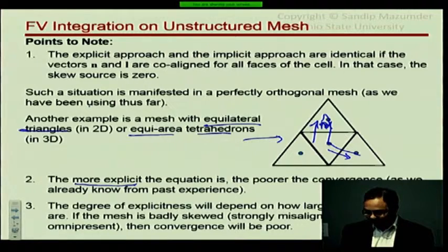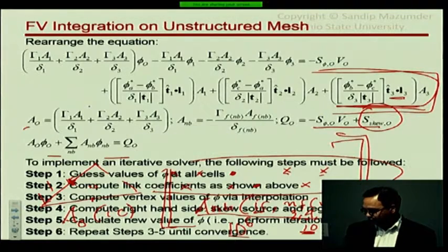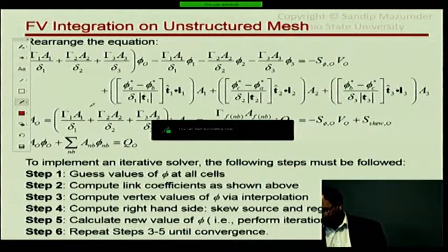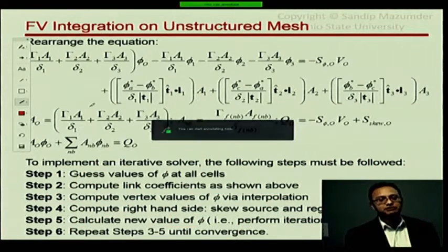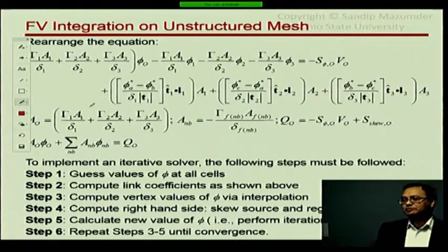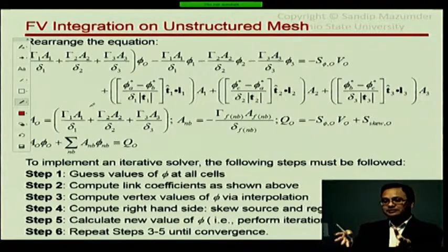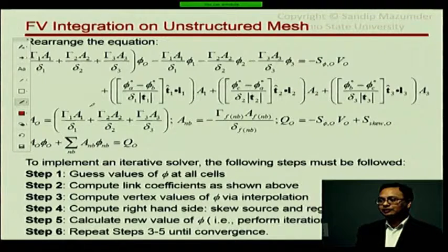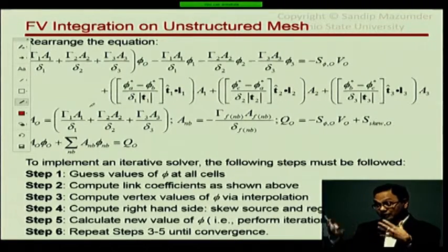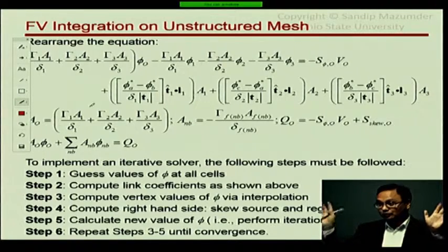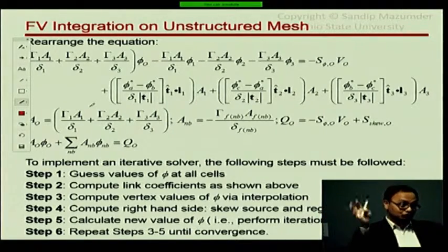Here's the thing I was talking about: partial convergence earlier on. If you use CG, for example, CG is like a black box. You get some CG solver from somewhere. You feed in the A matrix and the right-hand side vector, and it gives you back a solution. While it is solving internally in CG, you can't change anything. Your coefficient matrix and source terms are fixed.